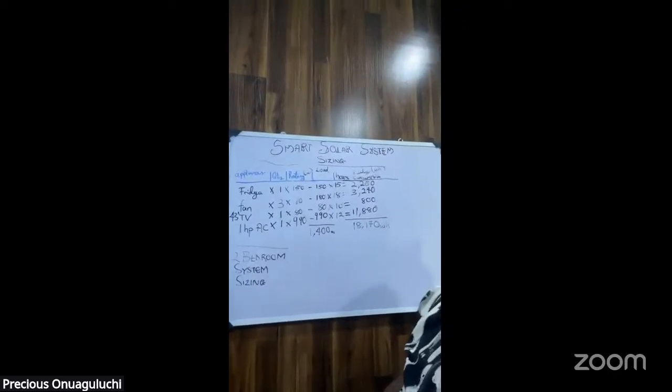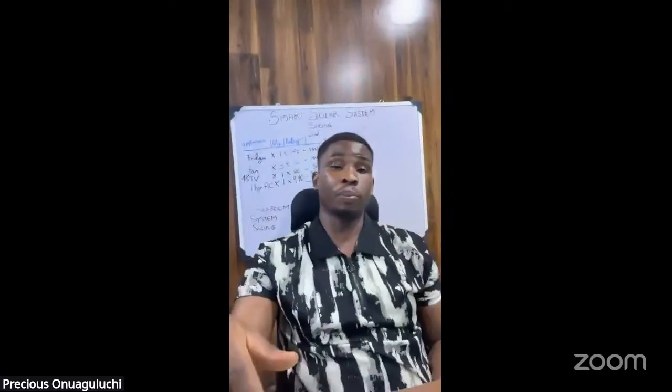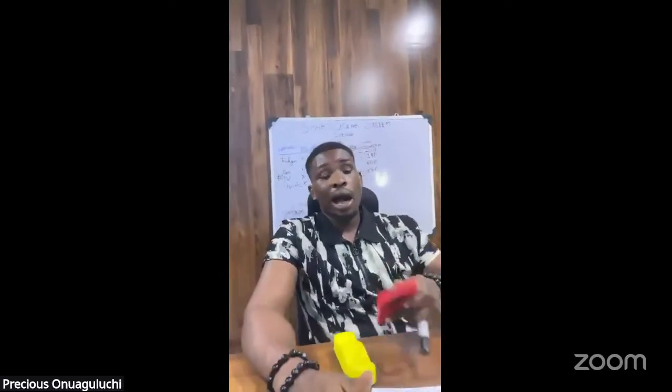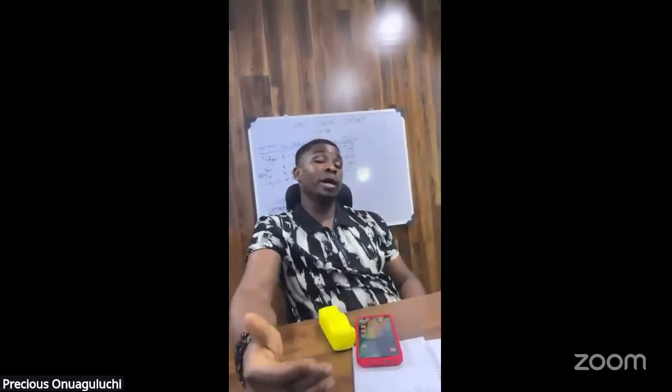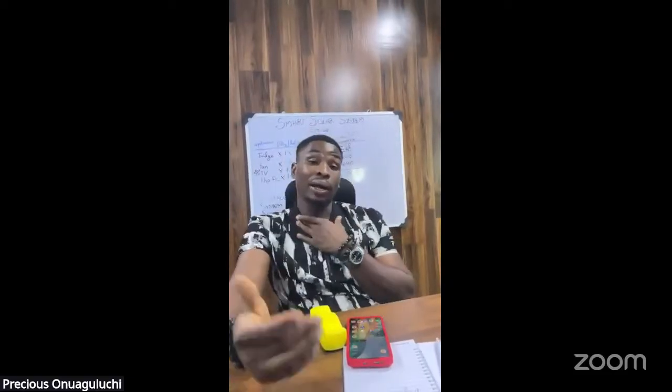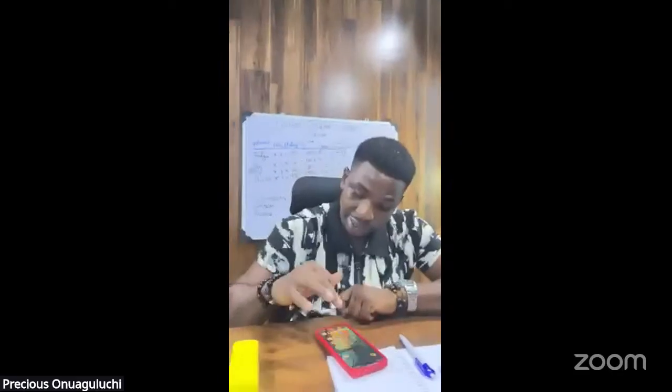Why is the battery sizing very important? It's very important because after the sun goes out, or when the sun is insufficient, the battery is what you depend on, right? So we're going to be calculating our nighttime consumption to ensure that we have enough battery to see us through the night. Okay. Now I'm going over to the next slide.